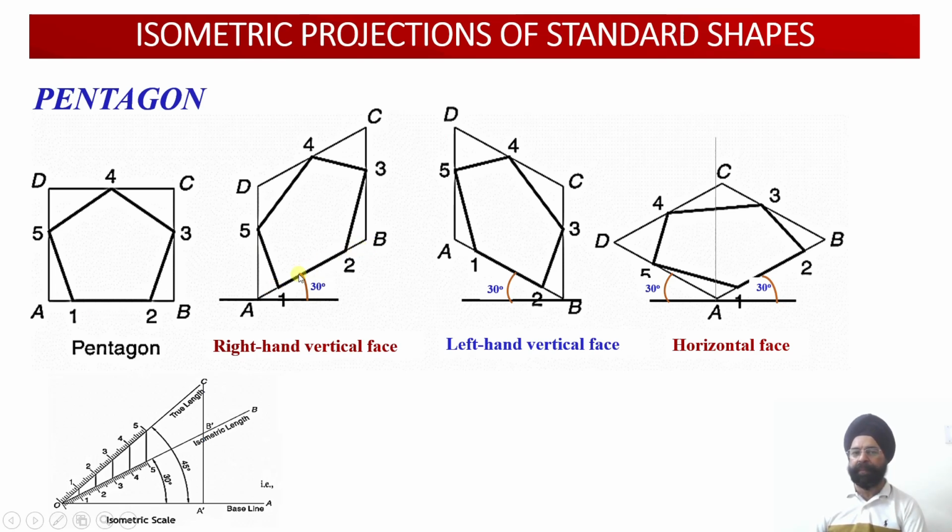So these distances I mark, I automatically get these 2 points. And please make sure all the distances which are marked over here will all be isometric lengths only. True lengths are not to be marked over here. So now you see, once I measure A1 and then I measure 1, 2 or I measure 2B, points 1 and 2 will be located along this isometric length AB.